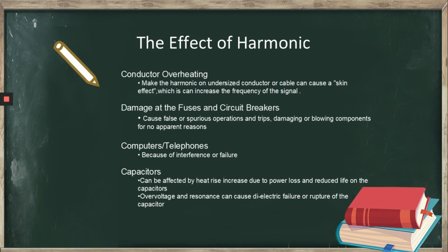Okay. The effects of harmonics. The first common effect is conductor overheating. Harmonics on undersized conductors or cables can cause a skin effect, which increases with the frequency of the signal. The second one is damage to fuses and circuit breakers. In this situation, high harmonic current can cause fuse blowing in the capacitor bank. The result is a loss of reactive power supply to the system, which can cause other problems.